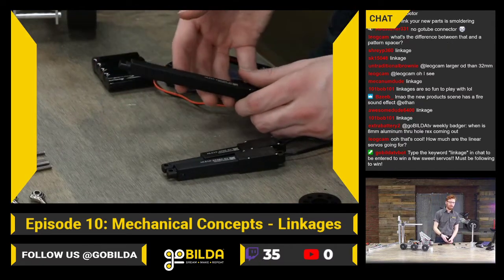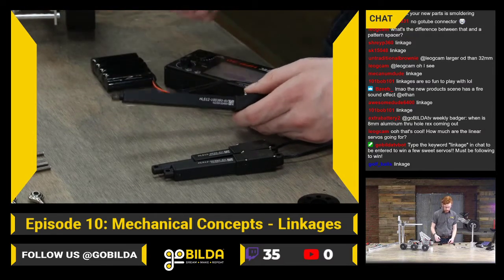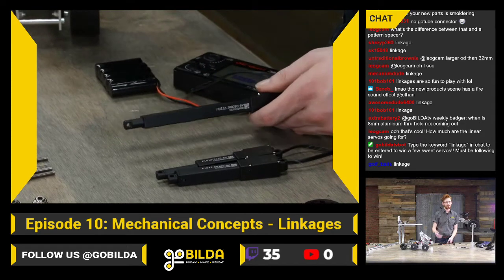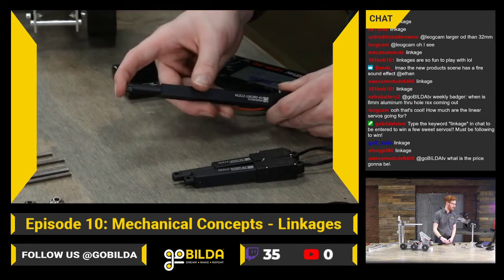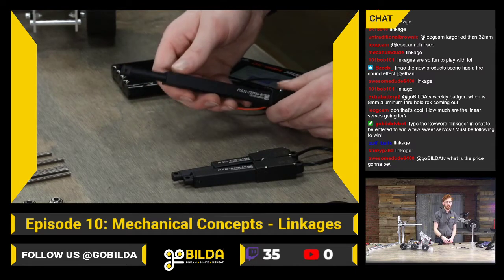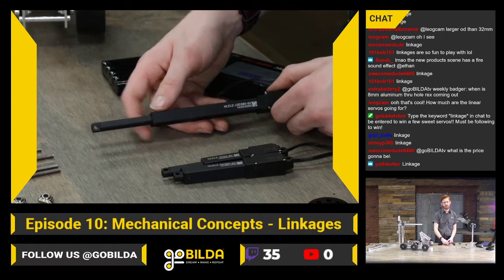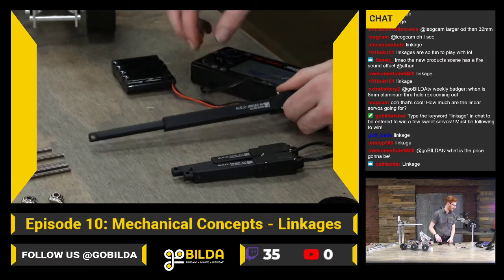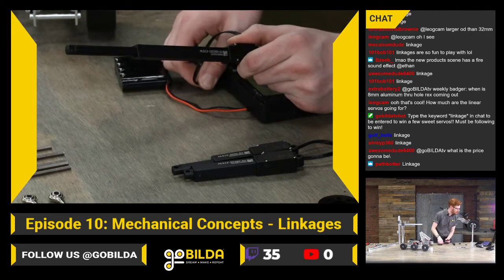These will pull about half an amp at stall, so they're definitely not a very powerful option, but they're a great option if you need to move something that doesn't necessarily have to be very fast. This is their slowest ratio, the 380 to 1, and it can definitely push a lot for its weight class and the amount of power it draws, but you can see it's really slow. It's very slow.